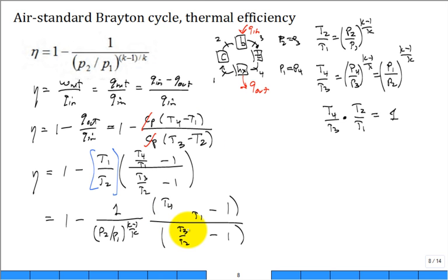So what we do here is we divide by T3 multiplied by T3, which didn't change anything. Then we divide by T2 multiplied by T2. So we just expanded what T4 over T1 is. And now you look and you say, aha, T4 over T3 times T2 over T1 is just 1. And so the whole numerator is exactly the same as the denominator. They're both equal. That ratio is 1.